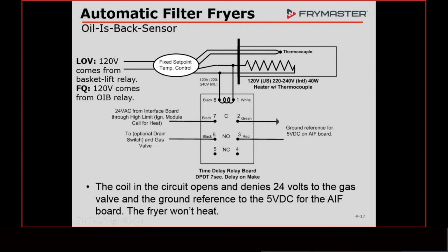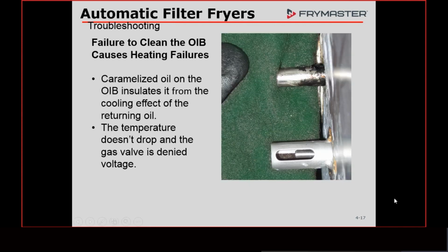Oh, yeah. On the next slide here, there is one more thing. This right here, those sensors, they need to be cleaned regularly. This right here, that's not that much. I mean, sometimes these things, because this is a heater and that new oil clings to anything hot, these things here get really built up with this carbon, and it slows the response down. Either way, either it'll make it not heat or it can make it heat when it shouldn't. So we just got to make sure that these stay cleaned.